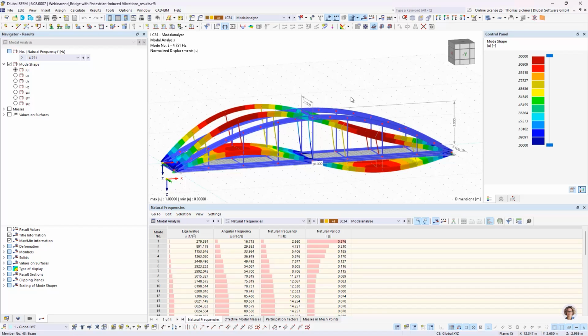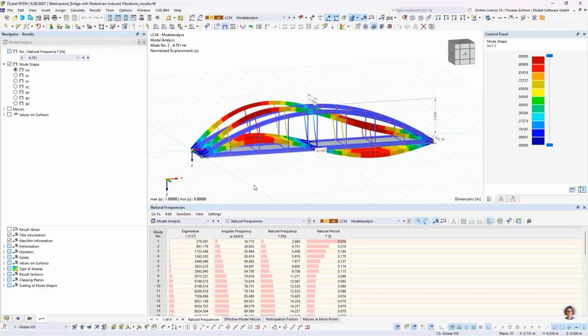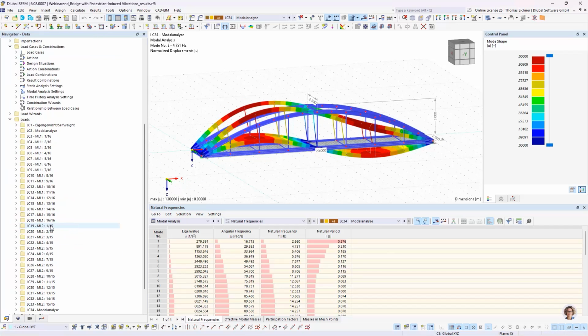So you could think about what you are interested in, what influence of some changes in the model you are interested in, and define that before the first calculation, and just go for 4 time history analyses with different structure modifications at the same time without losing too much calculation time. That's another tip there. And now we are almost at the end, I guess.